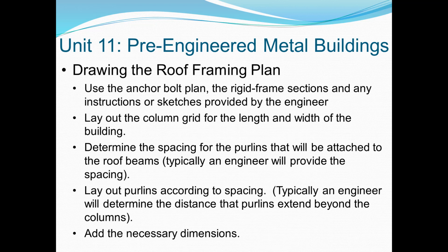Again, you start with your anchor bolt plan, the rigid frame sections, and any instructions or sketches provided by the engineer. You'll lay out the column grid for the length and width of the building, just like we did the other day. Laying out the anchor bolts was the main purpose for that.